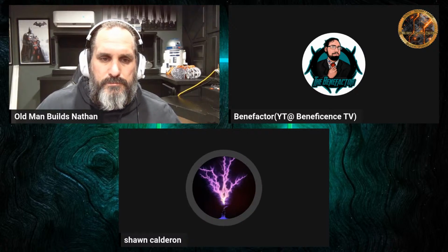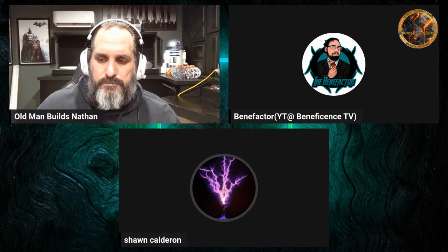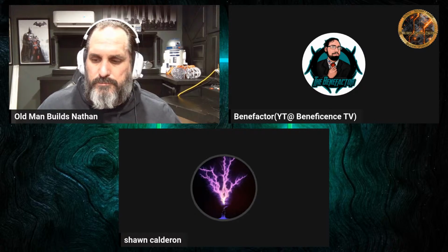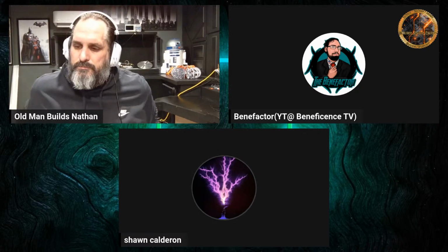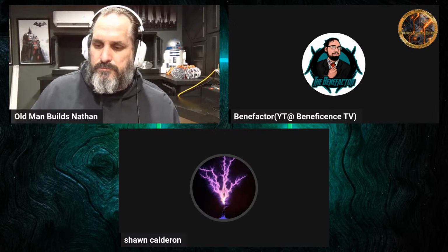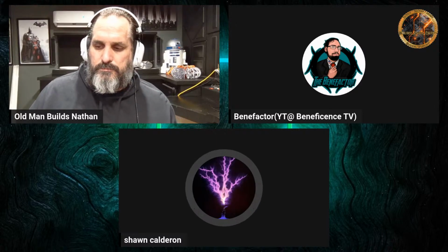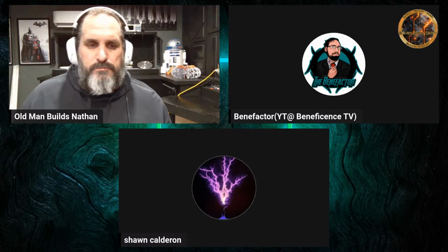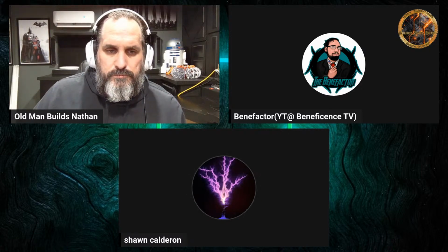Yeah, and I think we're all in alignment on this one, because when I was adding lights to the Slayer exciter circuit, I actually had my oscope measuring the frequency. And as I was adding light, or when I put the wire in the mud, as I was adding things, the resonant frequency was dropping. It got lower and lower and lower because they were all capacitors. A piece of mud's not a capacitor technically, a fluorescent bulb is not a capacitor technically, but they add capacitance to the circuit, driving down the frequency. I'm not sure if I shared that in the presentation, but that was noticeable in my experiments.